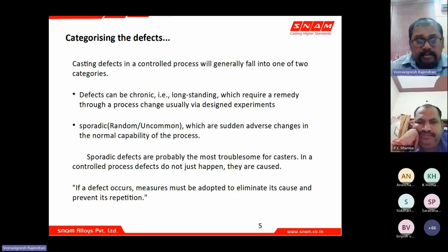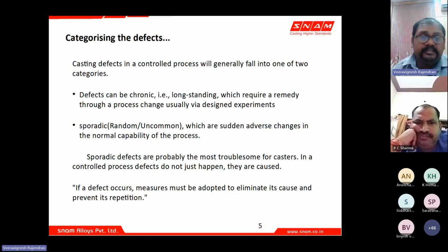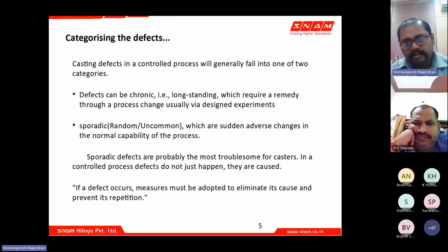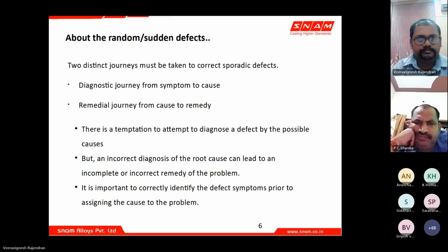might lead to some other defect, like less strength in the mold, leading to erosion in the mold while filling. So you start getting sand inclusions, then you start getting other related defects. The strength of the mold comes down, very remote location shrinkage can come up. So one cover up can lead to multiple defects. So we should always target understanding the cause of the defect, eliminating its cause, and preventing its repetition.